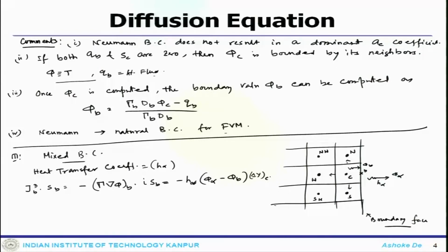So, here you got both the information in the mixed boundary condition, which is another way people call it a Robin boundary condition or mixed boundary condition, where you have both the Neumann kind of boundary condition given a flux and also the specified value is also provided. So, both of them act simultaneously at the same face.